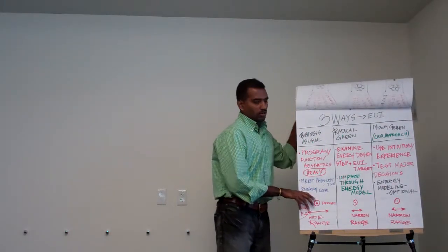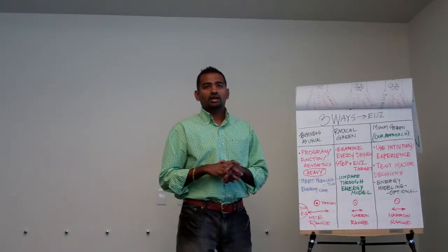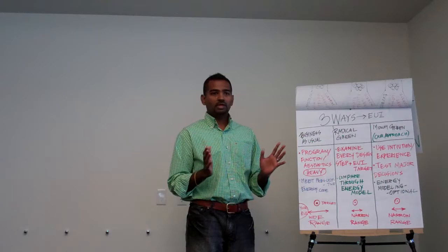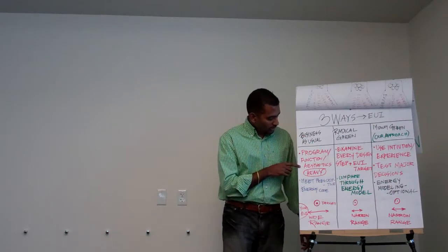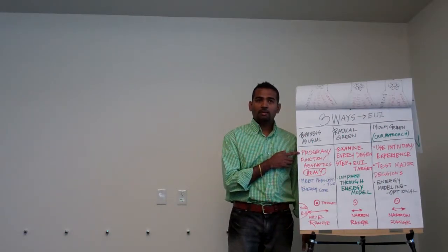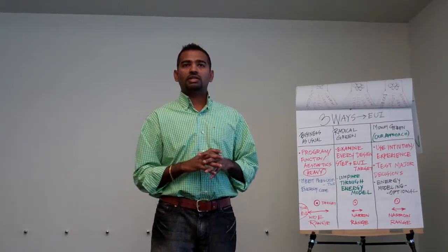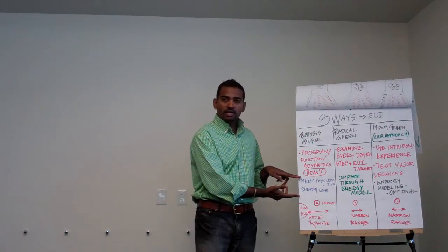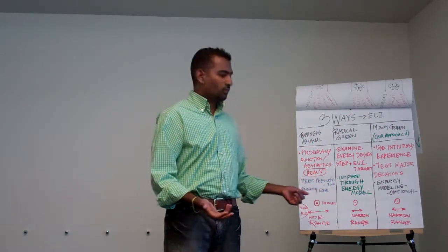Exactly. Okay. So I've been thinking about this EUI and how do we rationally approach this? Because we can't necessarily do this on every single job, right? So we have to have a medium. I can think of three ways to attack this problem. The first way is typically most of what our projects will be, which is we go with program, function, and aesthetics as our primary importance, and little importance to energy and energy consumption, okay? Because that might be the client's need or whatever. So we may meet the prescriptive requirements of the energy code. We have to, so we will do that.